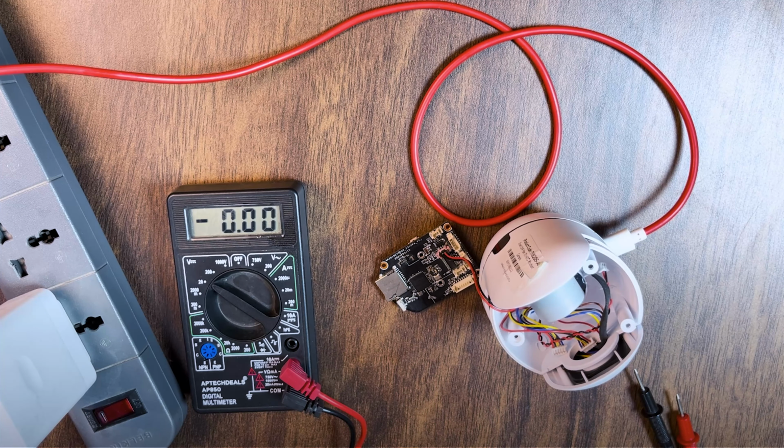Could be Picocom, could be some other thing, right? And via that you can see whether you're getting an output or not. If you do get an output, congratulations, you figured out which is the TX port, and naturally then the other port is going to be the RX port.